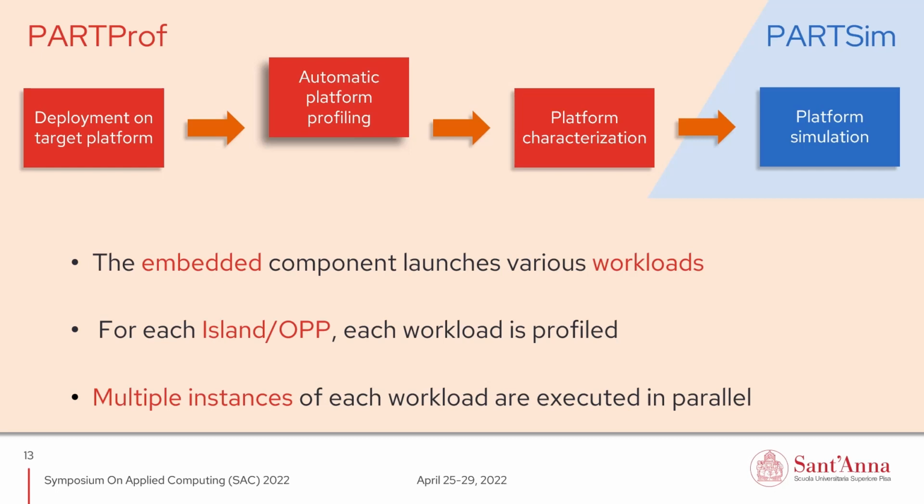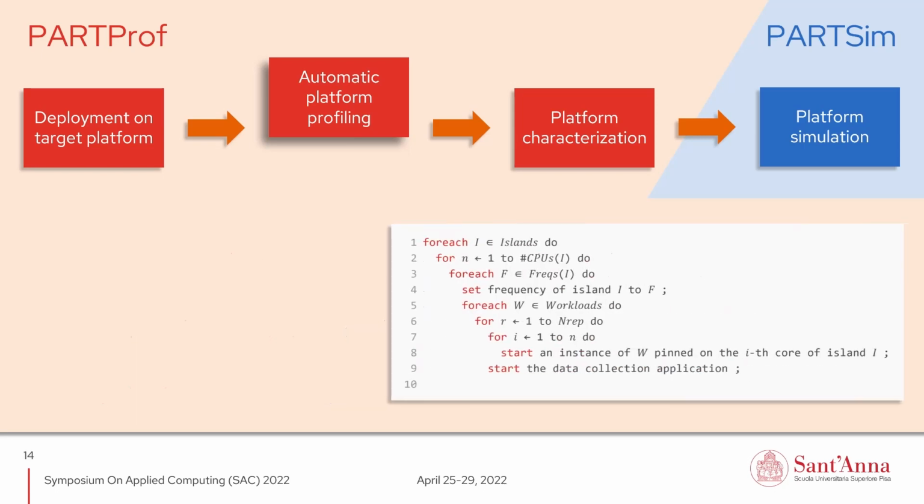Profiling is typically performed over each possible DVFS configuration for each core island on heterogeneous platforms, with the possibility to start one up to n instances of the same task. The possibility of running multiple instances of each workload is crucial, as we will see later during this presentation. In simpler terms, the profiler sweeps all possible combinations of the selected CPU island, CPU frequency, workload type, and the number of instances of each task to execute on the same island.